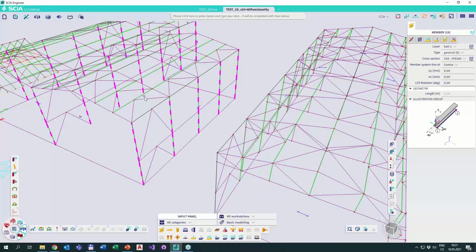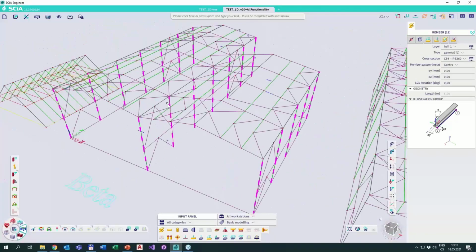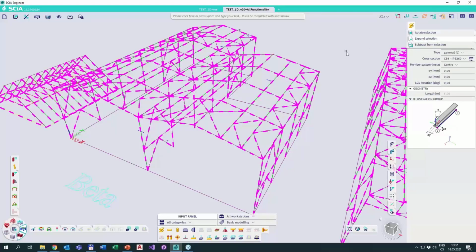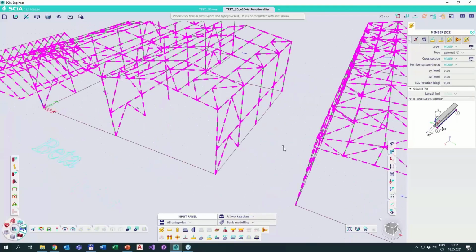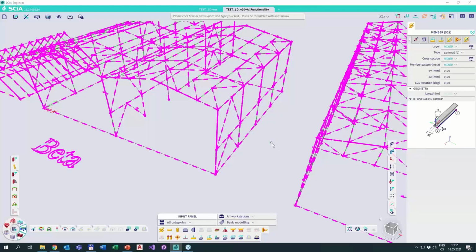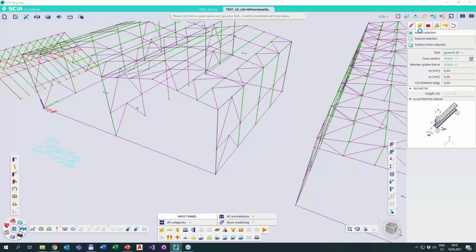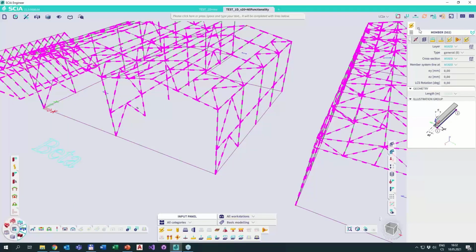So you can see that in this way, working with the actual selection from the property window was never easier. You can actually do the same thing while right-clicking on the whole group. So you can, for example, expand selection like this to select all 502 beams in this project, or if I just click Ctrl A to just select everything, I'm also able to just right-click on beams to deselect everything else.